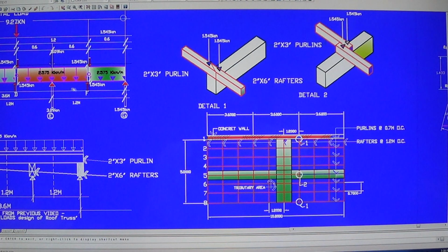So we're solving one, and what we get there is applied to every purlin and rafter as well. Here the reaction is only 1/2, since we're showing one purlin, but for the other half, in continuation of the purlin, there are going to be 2 reactions in there, 2 halves of reactions, both at the end of the rafter and the midspan of the rafter.